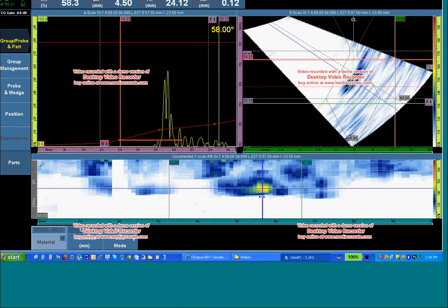When we teach weld inspection and weld flaw characterization, we generally promote 3 criteria. Location of the flaw. Was it detectable from both sides of the weld when that's possible, as a criteria 2? And the third criteria is the A-scan characterization, also the S-scan characterization, what it looks like.